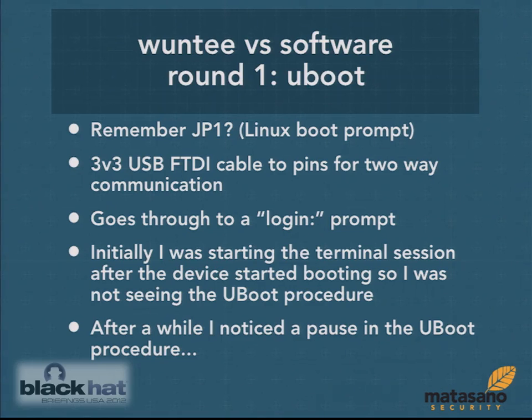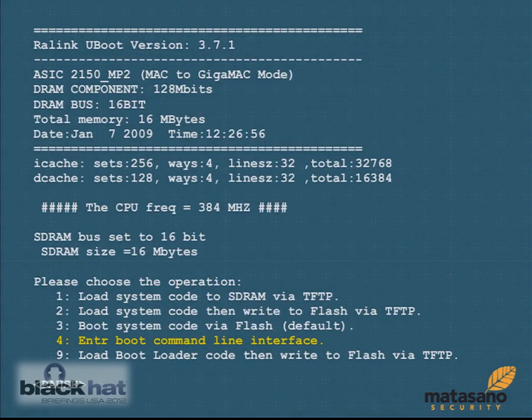What I was doing though when powering on the device was plugging in the device, then starting the terminal session, and so I was missing the whole beginning part of the boot procedure, and I was just getting to this login prompt. I was like, what? How? I tried guessing. Obviously, root didn't work, but after a while, I ended up keeping the terminal session open and then powering on the device, and I noticed this. The beginning of U-boot, and it paused for like 2 seconds that you wouldn't really notice, but after booting it about 50 times, you can actually see this.